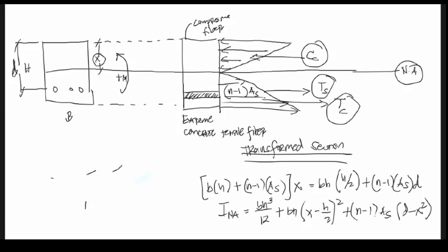So moving on. Your formula now for the concrete stress in compression. Concrete stress in compression, that is f sub c sub c, or F sub CC, is equals to the actual moment multiplied by X over I_tr.